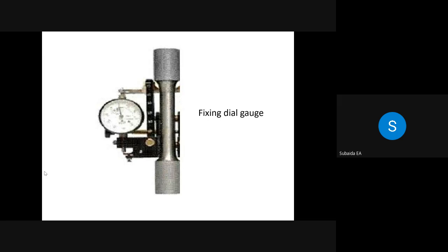The extensometer that is there in our lab now has a gauge length of 5 centimeters. So there should be two sharp punch marks in order to fit the extensometer. And what extension is taking place for that particular length, we are measuring using this dial gauge. It will show its least count, maybe 0.02 centimeter or millimeter. There are extensometers with different least counts. We have to note down the least count of the extensometer. Then only we can complete the calculation.